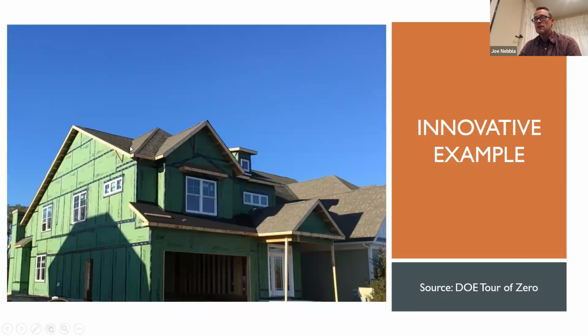Same thing here. This is an exterior insulating product. It's actually a structural sheathing product that has an insulation with it. I'm not sure if this is the R5 product or whether it's something lower than that, in which case you would need even more cavity insulation or to do some kind of UA trade-off to get this wall to comply in combination with cavity insulation. If it is R5 in this product, then you would only need the R20 in the cavity.